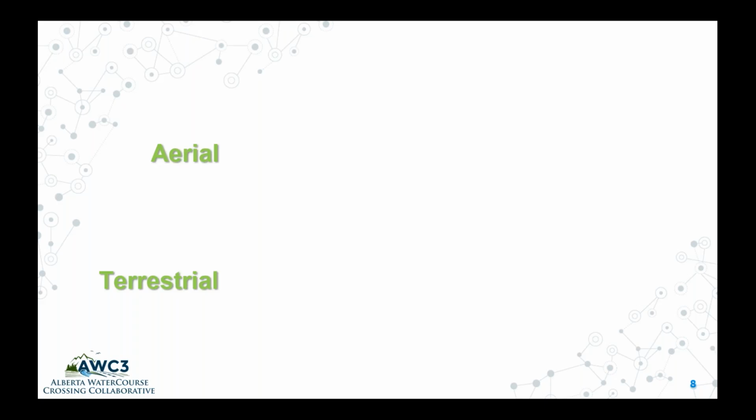In the last 4 to 5 years, drone-mounted LiDAR has been developed and has been used commercially. It is very promising, I would say, but it still has a lot of noise and data limitations that need to be cleaned out. I guess they will be actively developed by the vendors in the near future. But aerial LiDAR using helicopters or large fixed-wing planes is quite mature.